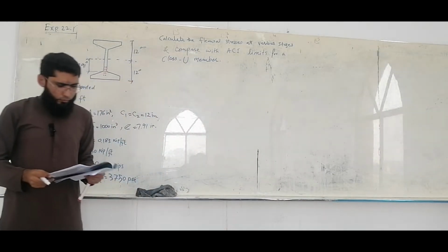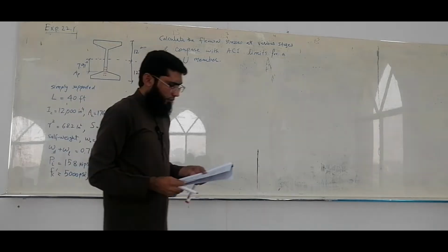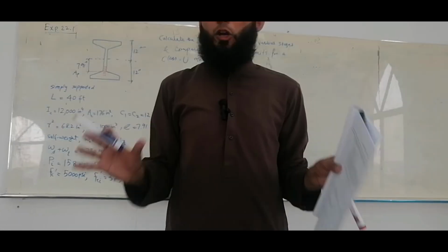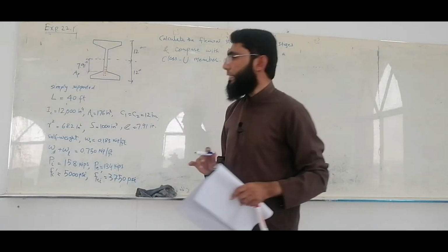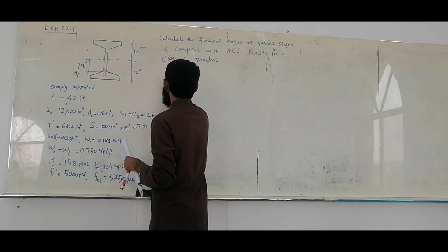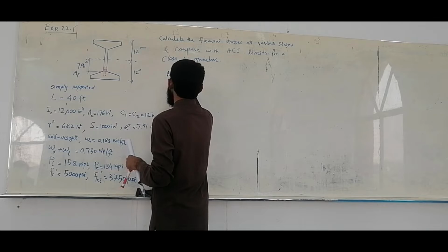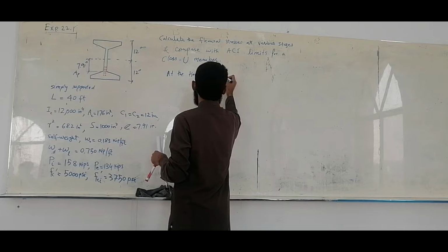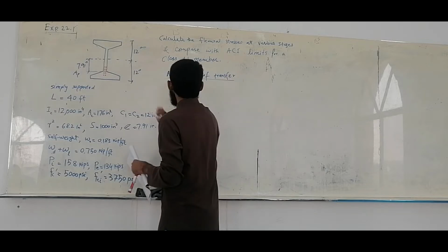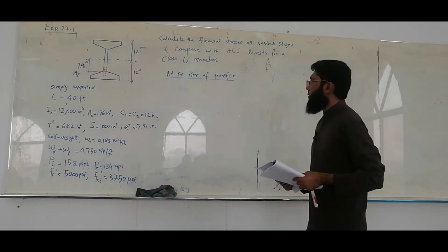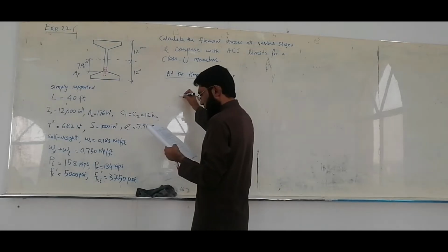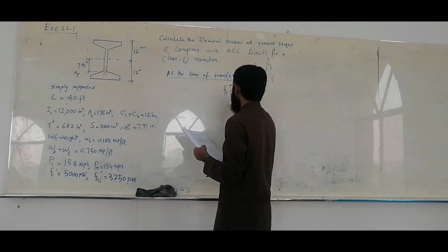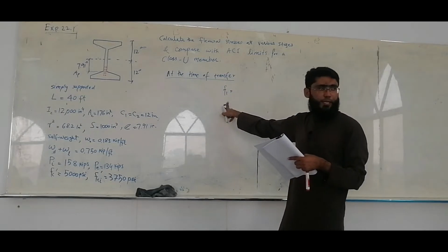Now the first thing to do is you have to calculate the stresses due to the pre-stressing force alone. So the first stage is at the time of transfer. At the time of transfer, the stresses would be F1 at the top. F1 for the flexural stress at the top.